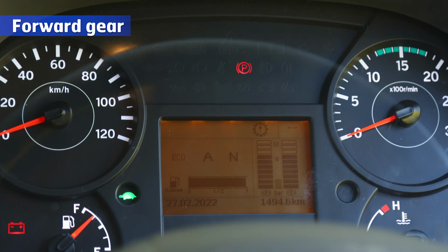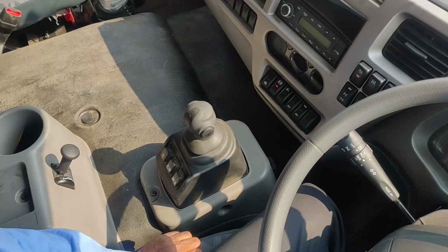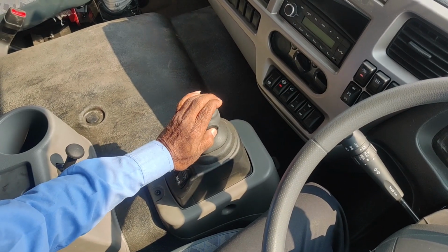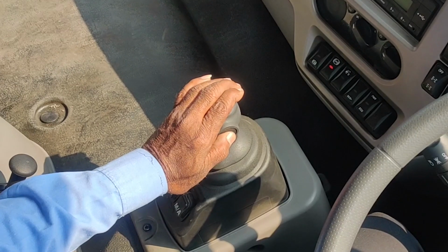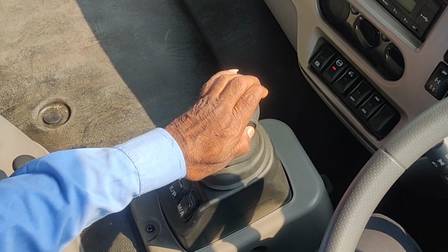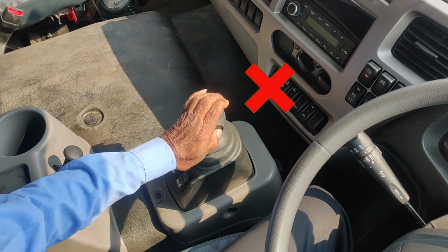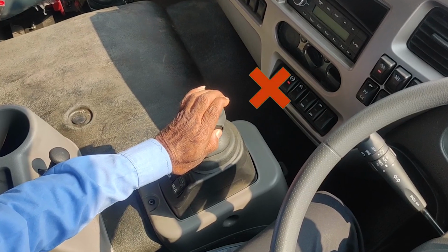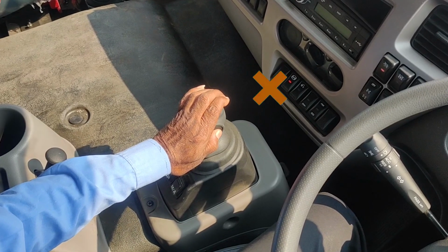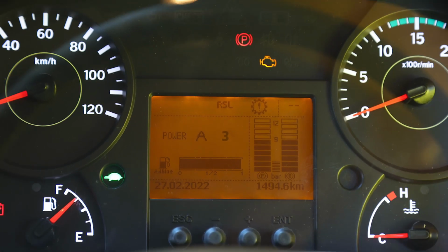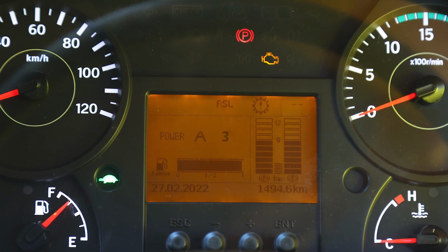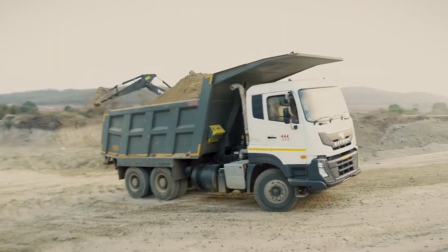Forward gear. When the gear is in neutral, forward start gear is requested by pressing the function button, F button, of the shift lever unit and simultaneously moving the shift lever forward. Crawler and first gear is the highest available gear as starting gear. A shift request to a gear higher than crawler and first gear as starting gear will be rejected. In auto mode, the default start gear is selected based on the calculated load.